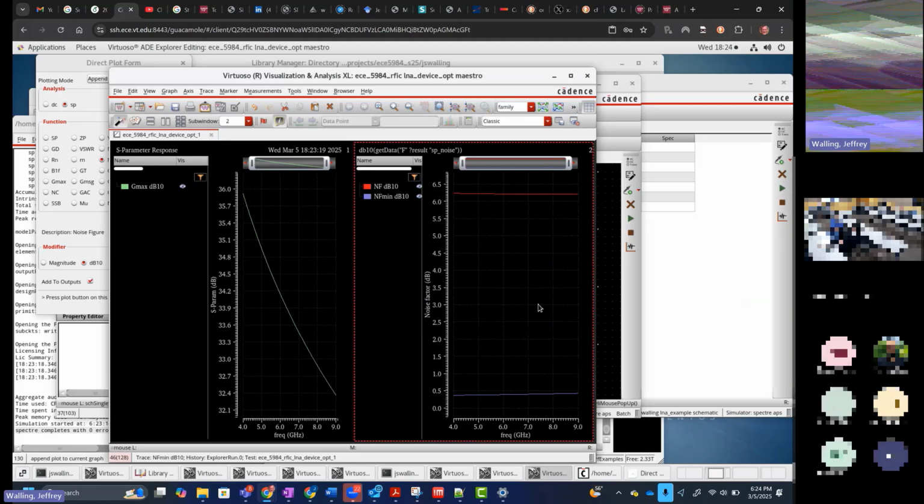All right, you can see quite a stark difference here. The minimum that the amplifier could achieve is something like 0.4 dBs, and with the impedances that are presented to it right now, it's about 6.2 dBs. You know that your design is good when your actual noise figure is getting close to the minimum achievable noise figure.